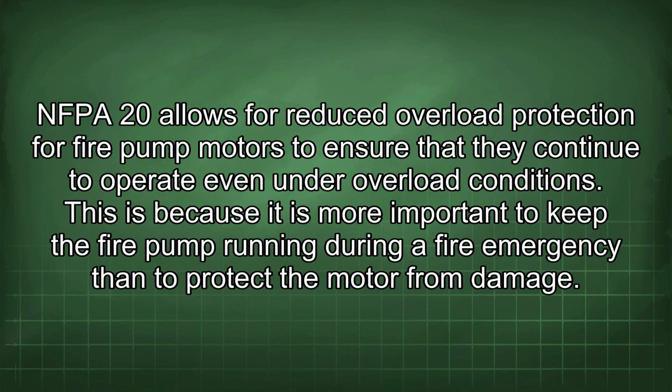NFPA 20 allows for reduced overload protection for fire pump motors to ensure that they continue to operate even under overload conditions. This is because it is more important to keep the fire pump running during a fire emergency than to protect the motor from damage.